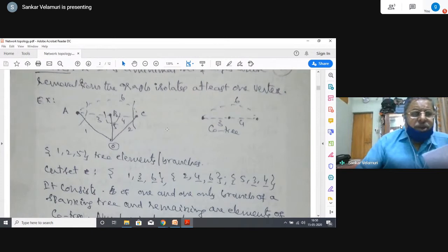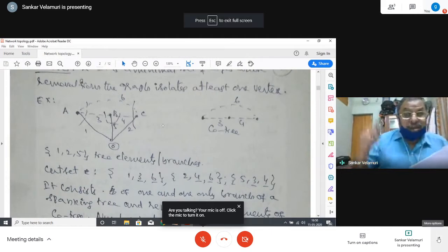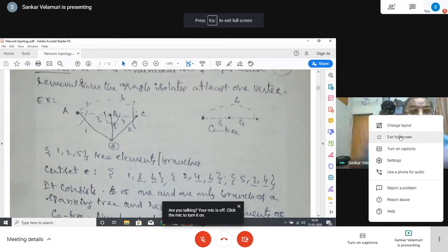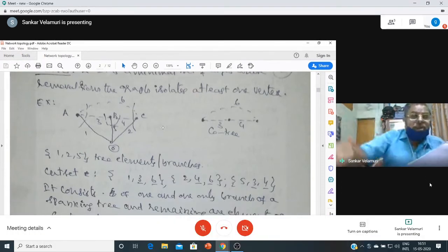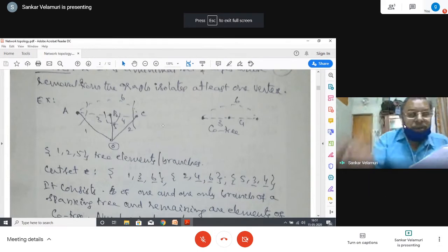The fundamental cut sets only will be with respect to the tree branch. That is one of the fundamental definitions. The number of tree branches equals the number of fundamental cut sets, equals the number of node pair voltage equations. That theory has evolved from graph theory. So for solving circuit problems, it is related because of this. It is not a method. It is only a process of identifying the minimum number of equations required for solving the problem.